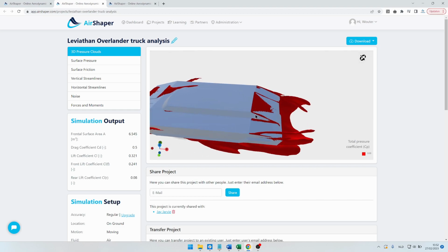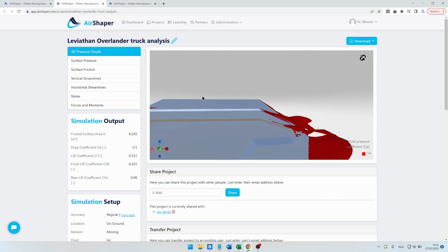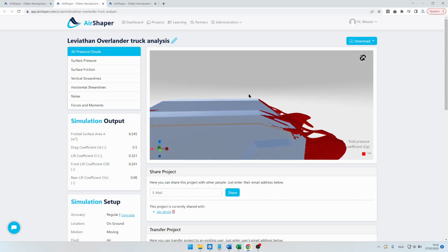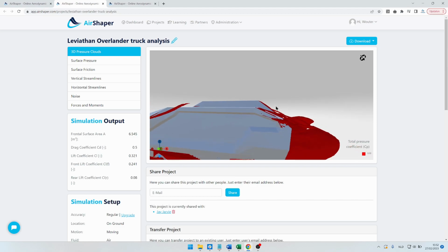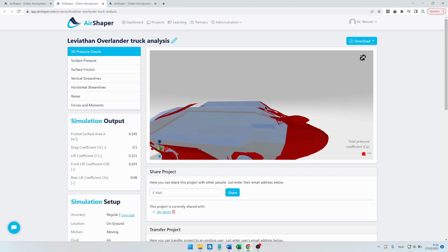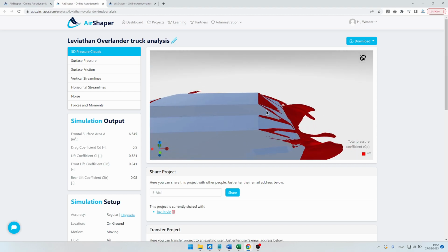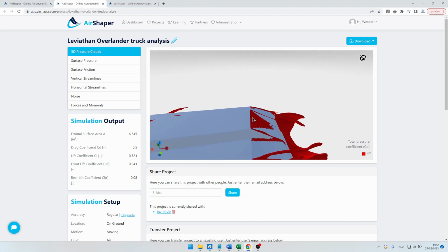Instead, we're going to look at what happens at the top of the Leviathan. So we have this, again, very practical shape, very good for structural components to weld the frame on the inside, but the sharp corner between the horizontal top of the roof and this inclined shape that actually closes the overall shape of the Leviathan is a sharp one that triggers flow separation. Very interesting to see. You even see some flow patterns similar to the Ahmed body, which is actually a validation case for automotive objects. Long way back, it was designed.